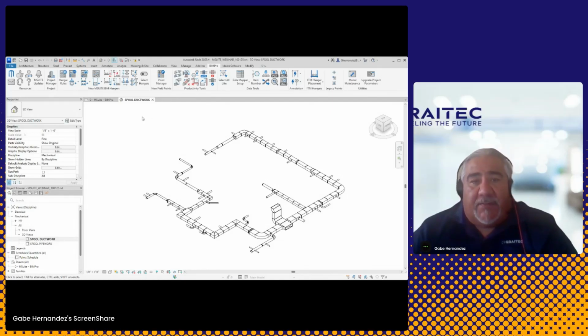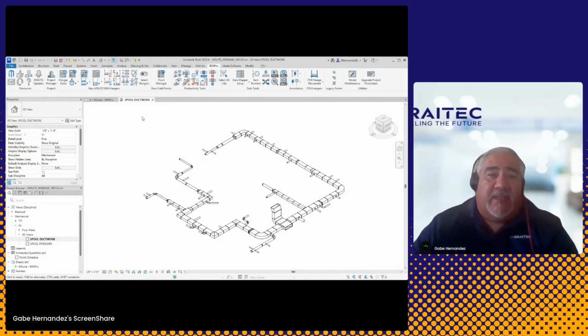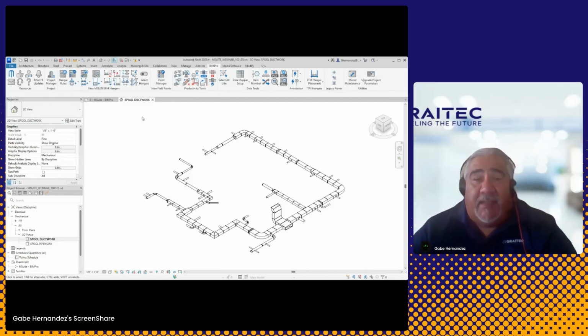There also is a converter here, Convert Spools, and what this allows you to do is take spools that were generated in the other solutions for spooling, like Fabrication, CAD-MEP, or Siskiyou, and convert those into BIM Pro spools. So this tool will allow you to take an existing project, or if you're moving from CAD-MEP or from Siskiyou into Revit and MSUITEs, you'll be able to convert what's existing into the BIM Pro world with this command.